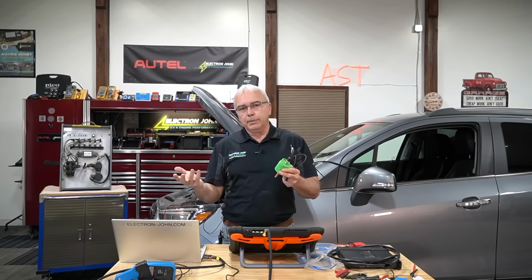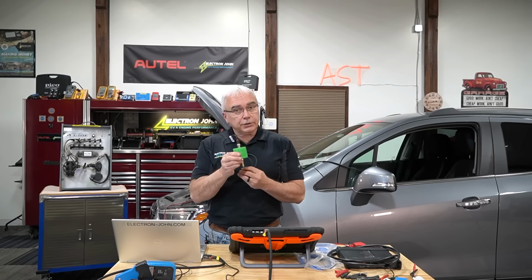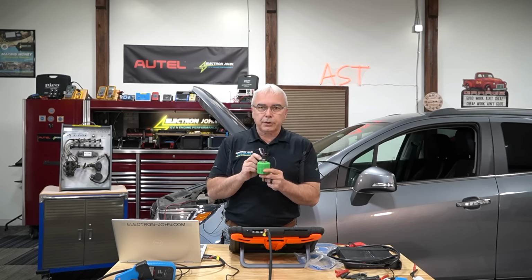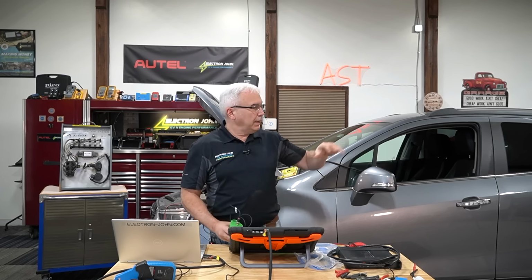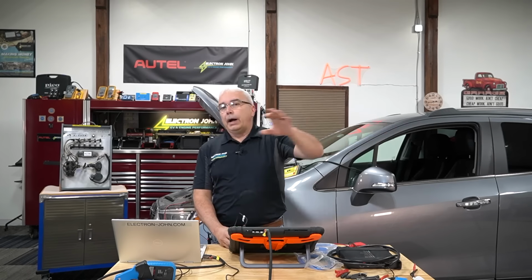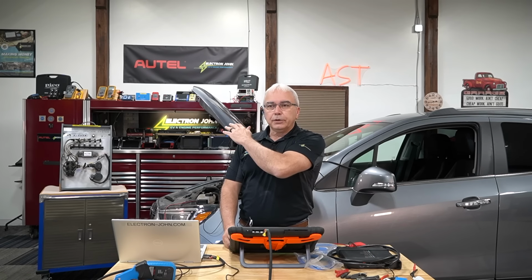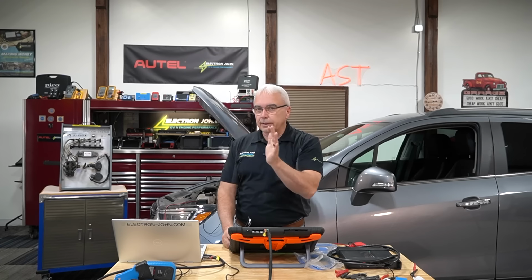And then I've got the less expensive style. This one here, I cannot put inside of a combustion chamber because the pressure would be too high. It has a little vacuum diaphragm inside of it, and if I try to put 150 PSI of pressure through there, I'm going to rupture that diaphragm. But this sensor is a pretty universal type of sensor. I can put this in and measure lower types of pressure or vacuum readings, like in the exhaust tailpipe, possibly into a vacuum hose, or if there's blow-by in the engine.